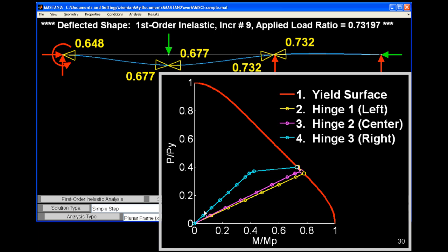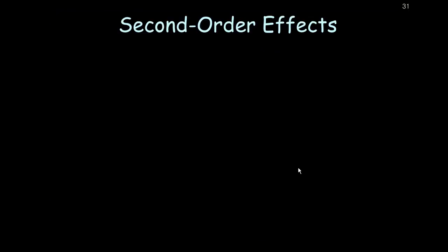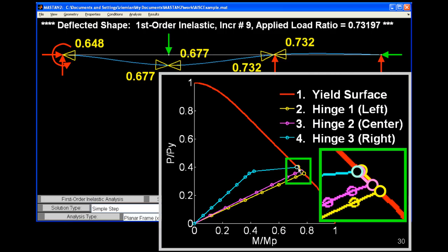Now if we count 6 increments on the right side of the beam, we're about here. So we don't have a plastic hinge at 65% of the loading, but what's going to happen is we are going to get that plastic hinge forming at the left side, dramatic loss in stiffness in the structure, and we start immediately seeing this cross-section over on the right side dash off and hit almost 2 load steps later right against the yield surface. So I think, Brent, I'll stop there and see if you have any questions for me.